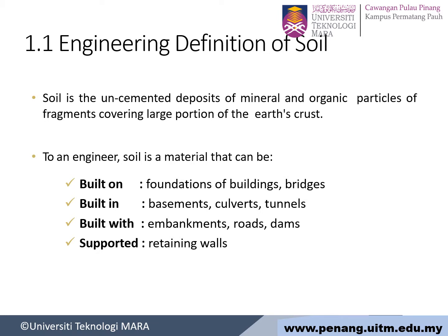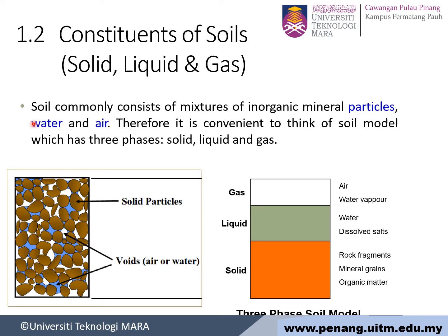Firstly, we go to the engineering definition of soil. Soil is an uncemented deposit of minerals and organic particles or fragments covering a large portion of the earth's crust. To an engineer, soil is a material that can be built on, built in, built with, and supported. For example, built on: foundations of buildings and bridges. Built in: basements, culverts, tunnels. Built with: embankments, roads, dams. And it can be supported by using retaining walls.